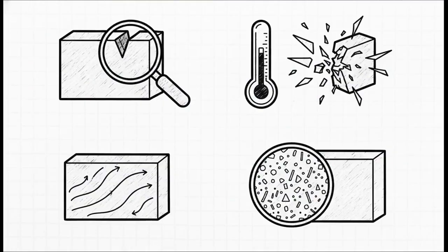However, as an engineer, it's vital to know that IZOD results aren't just magically absolute numbers. They are highly sensitive to several testing variables. Specimen thickness and how flawlessly smoothly that notch is cut play a huge role. A jagged notch ruins the test. Temperature is massive too. As we talked about earlier, lowering the test temperature drastically reduces impact resistance as the material approaches its glass transition and becomes brittle.